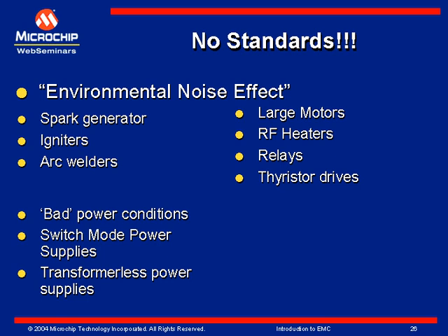Otherwise, you need to find a worse industrial environment, or worse environment for your product, and do on-site testing. And it's much more difficult to do debugging in that environment because you cannot control it, you don't know what kind of noise you are getting and how it's being coupled to your system.